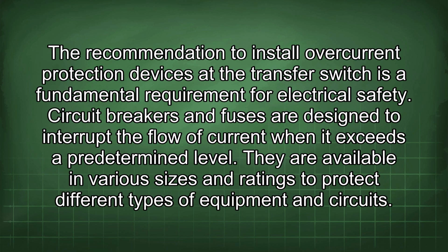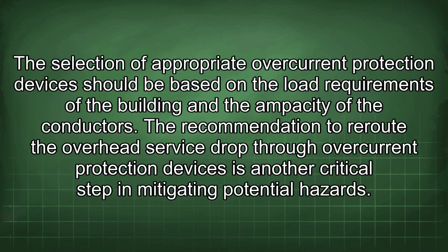The recommendation to install overcurrent protection devices at the transfer switch is a fundamental requirement for electrical safety. Circuit breakers and fuses are designed to interrupt the flow of current when it exceeds a predetermined level. They are available in various sizes and ratings to protect different types of equipment and circuits. The selection of appropriate overcurrent protection devices should be based on the load requirements of the building and the ampacity of the conductors.